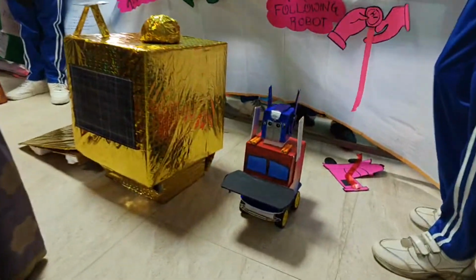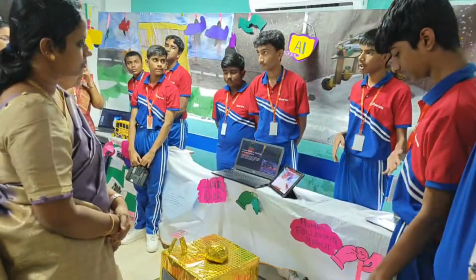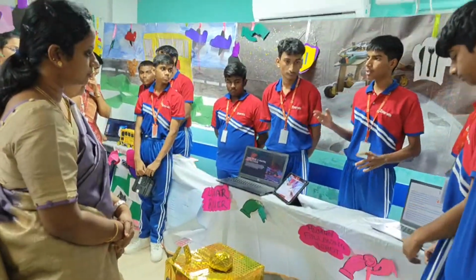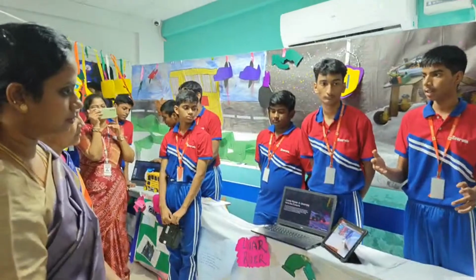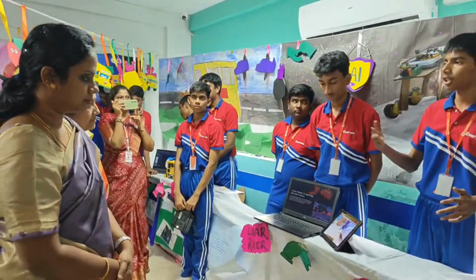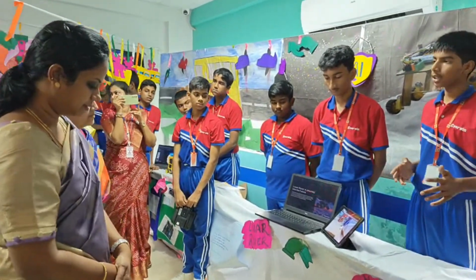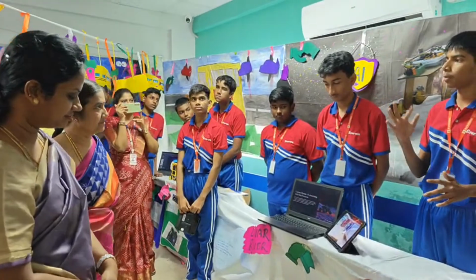This is a microcontroller board based on the ATmega328, and it has 14 digital input and output pins and 6 analog inputs. And we have an IR sensor, which is a proximity sensor used to detect objects in front. An ultrasonic sensor is used to measure the distance of an object by emitting ultrasonic sound waves. The range of it is about 40 to 70 kilohertz. And a servo motor is used to rotate the head approximately up to 180 degrees.